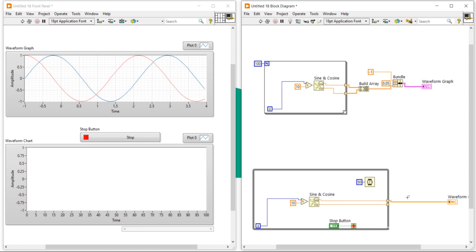Okay, so that is a waste of our program. Why? Because if you want to run your program for 2 minutes, 5 minutes, 10 minutes, you have to use the waveform graph here. Why? Because you want to display that specific 5 minute data, 2 minute data. You don't want to see each and every second generated data. Suppose I run the program, now you can see we are not getting any data right now. When I press the stop button, then we will get this data. So what is the use? That means we are not able to see the current time and run data.